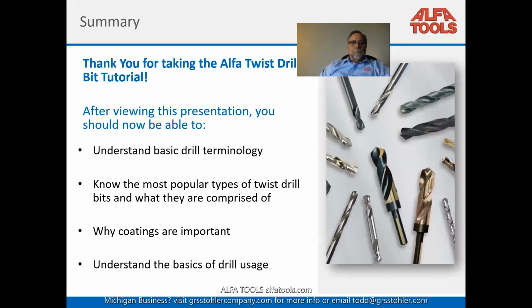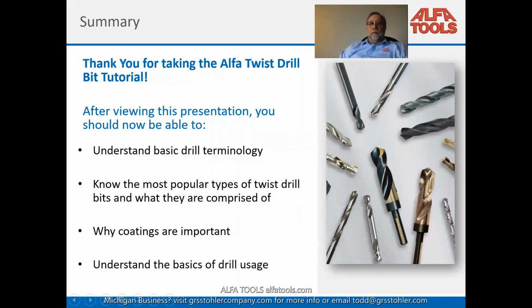What else do we have? Okay, folks, in summary, we appreciate you taking this and dialing in. It's a pleasure for me to just kind of narrate this. And hopefully you can understand a little bit of basic terminology, you know, a shank, what's the shank, the flute, the point. Yeah, you know, the most popular types of drills. I think you have an understanding that coatings are important. Especially if the guy says, hey, I've got 10,000 holes I've got to do this month. Then we start talking about carbide and coatings and how do we help the customer with cost per hole instead of, hey, my drill's 89 cents.